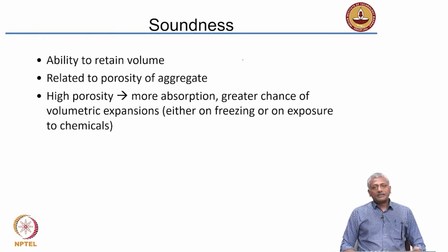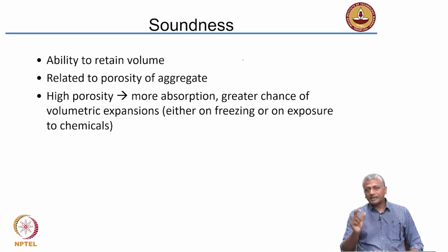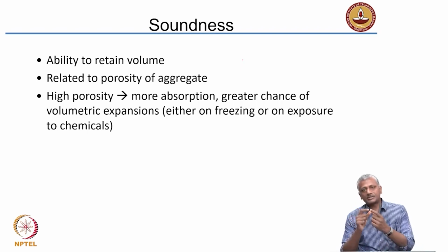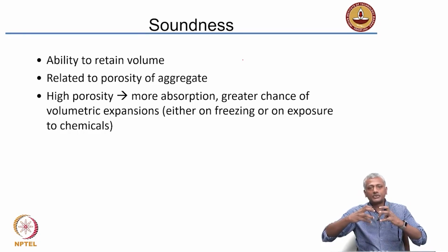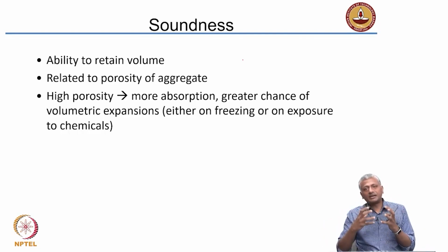Now, one of the other important properties of aggregate is its soundness. As I said, soundness is the ability for the aggregate to retain its volume. So, aggregates are porous, right. So, they are going to start taking in water, sometimes some chemicals, and these chemicals may leave behind some crystals, and these crystals forming inside the pores could cause the aggregate to expand, and if the aggregate is weak, it will start cracking. So, soundness is tested in a similar way.